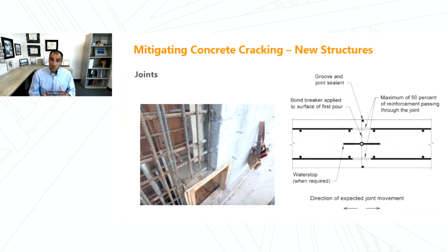The other thing we can do is accept the fact that we're going to get our shrinkage, and now we can provide some joints or places that we pre-engineered to have our cracks occur at.